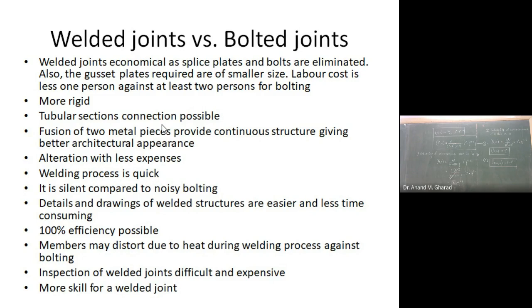Now, coming back to this splice. What exactly is a splice plate? Look, when two columns or vertical members are to be joined, we can provide a monolithic one, no problem, but there is a height limitation. We can manufacture or fabricate a column in the vertical position up to 10 meters. But in multi-storied structures whose height is more than 50-60 meters, if we want to connect the columns to each other, then there is a provision.